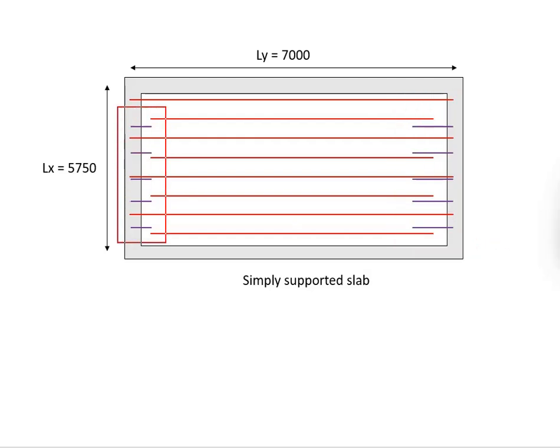Now, you cannot simply put the reinforcement bar like this, as there will be issues with the development of the stress and transfer of the stress between the reinforcement. If you put the reinforcement here without any lapping, it will be as if in these regions there is no reinforcement. You need a certain lapping length for the stress to effectively develop.